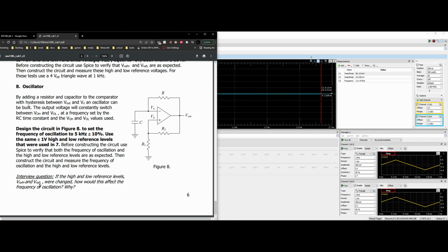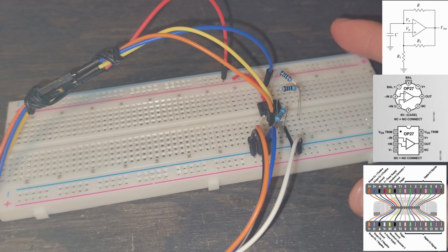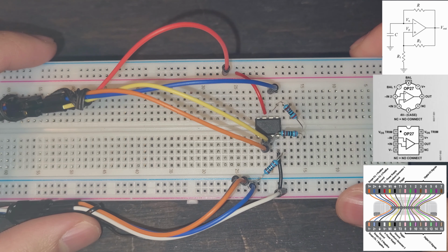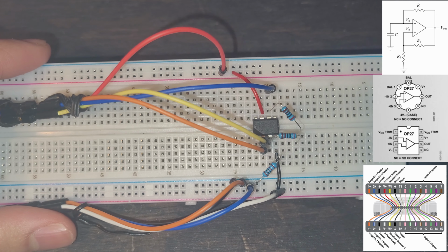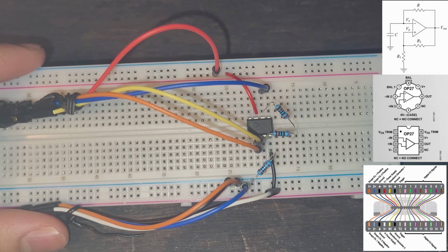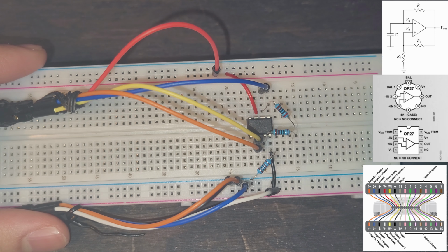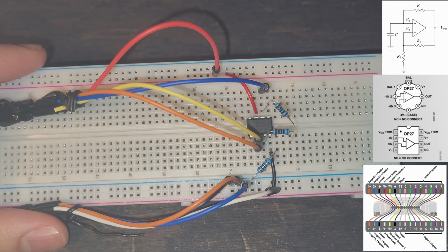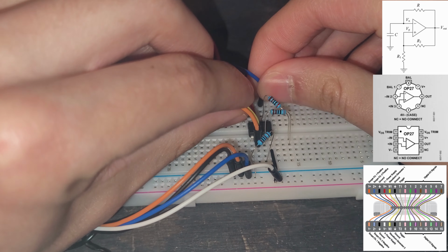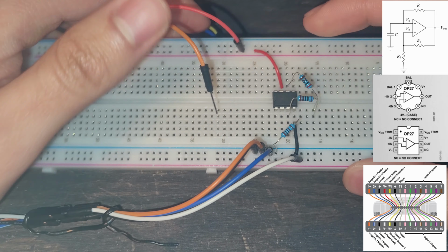And so now with that, we can look at our breadboard. Looking at our breadboard, we have the following circuit. Make sure that our wavegen is off before you start doing this, otherwise we might have a short circuit. So our connections, we're going to check them. Let's remove these wires so that we get a better look at our breadboard.